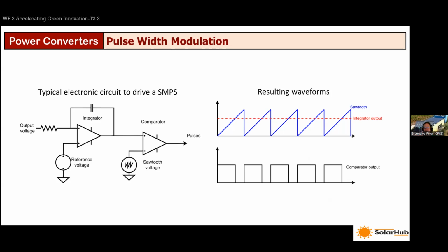I mean, it eliminates the error. So if we give the command here for a specific voltage level, 12 volts, for example, and the output voltage is 11, the circuit is forced to increase its output voltage in order to eliminate the integrator error, right? That's how, in a nutshell, this integrator works, and its scope here in this PWM scheme.